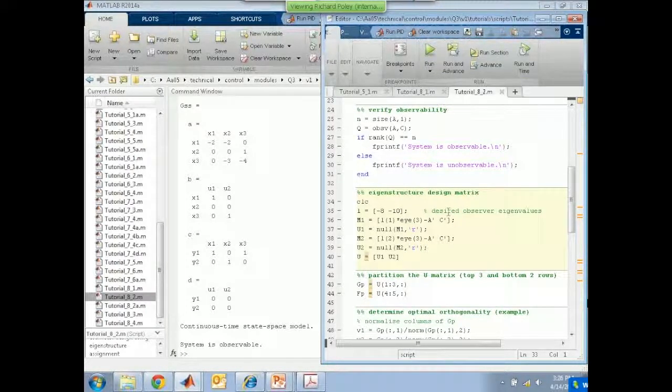And now we're going to choose the eigenvalues. Now, just to make things difficult, I've chosen a pair of repeated eigenvalues. I want -8, -8, and -10. And you can do that, but you're slightly less flexible in your selection of the eigenstructures because you've got 2 of these eigenvalues rather than 3, and so you're going to end up with 4 columns rather than 6, because each eigenstructure has got 2 columns because it's a 2-output system, but you've only got 2 eigenvalues instead of 3.